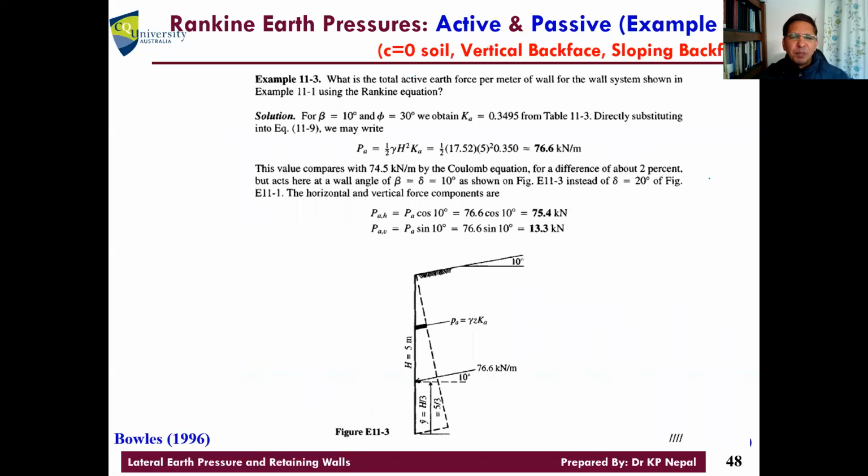Okay, so there is a very simple tutorial. I'm not going to do that. A simple tutorial based on what? There is a sloping backfill. That's it, right? Still the wall is vertical. Yeah, and then as I said, the pressure distribution is always like this. Use the same equation, you just need to do the Ka calculation. Ka, the active pressure coefficient, there is a formula, right? Very long formula now. We don't just use (1 - sin phi) divided by (1 + sin phi). All right, just use the Rankine equations here. Make sense? You can check this. This is a very simple formula.